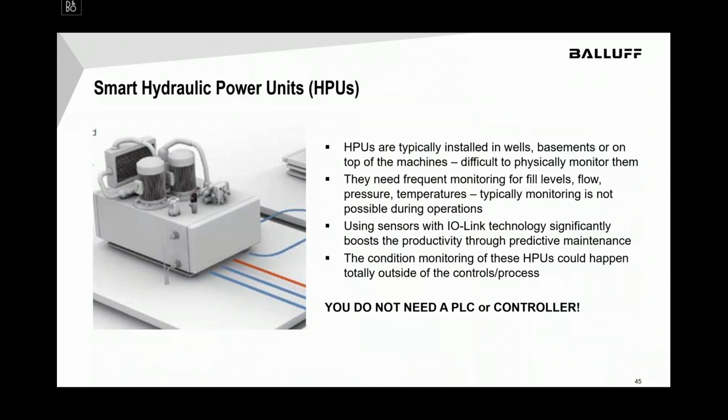HPUs is another area where IO-Link actually makes sense. And this is actually bringing us closer to that IIoT world. A lot of times these hydraulic power units are installed in wells or basements or some areas which are hard to get to during operations. And manually, somebody has to go to all these HPUs to check the oil levels, check everything is well with them. Frequent monitoring is required. Well, in order to monitor those variables, a lot of times you have to stop the machines so that somebody can go into the basement or the wells and check all these levels.